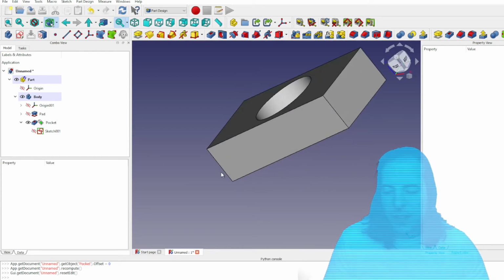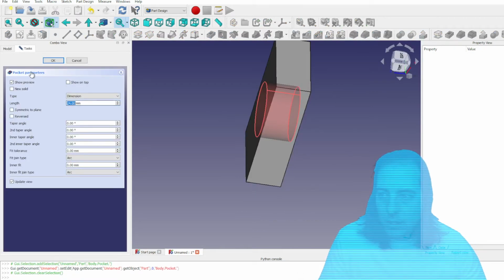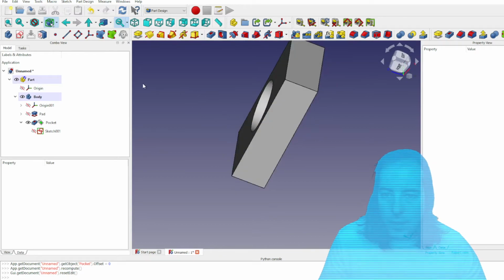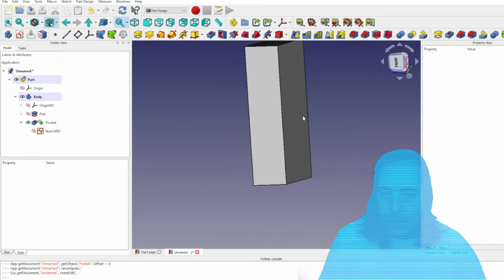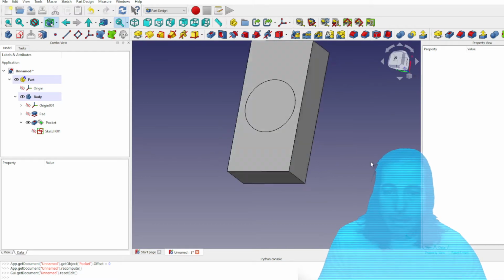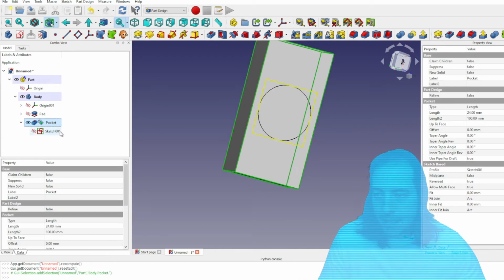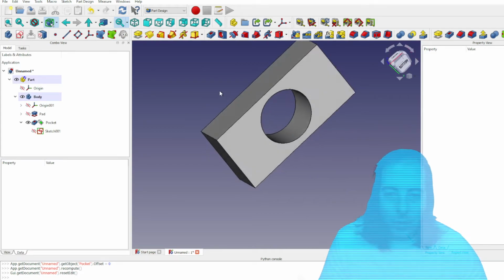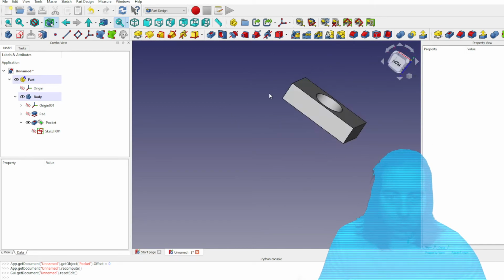And there's some other stuff that you need to do to make sure that the wall on the bottom is thick enough. Let me show you what happens if you reverse it. So if you remember, we have the sketch going that way, the hole's going that way. And if you reverse it, you guessed it. Look at that. So it started right here and it went the opposite direction. So it ended up not really doing anything. I mean, it just got this line right there. If you printed that, you might get a little weird imprint right there, a little marking, and it might not be too pretty. All right, so reverting back to our original decision, there is your pocket into your square hole.